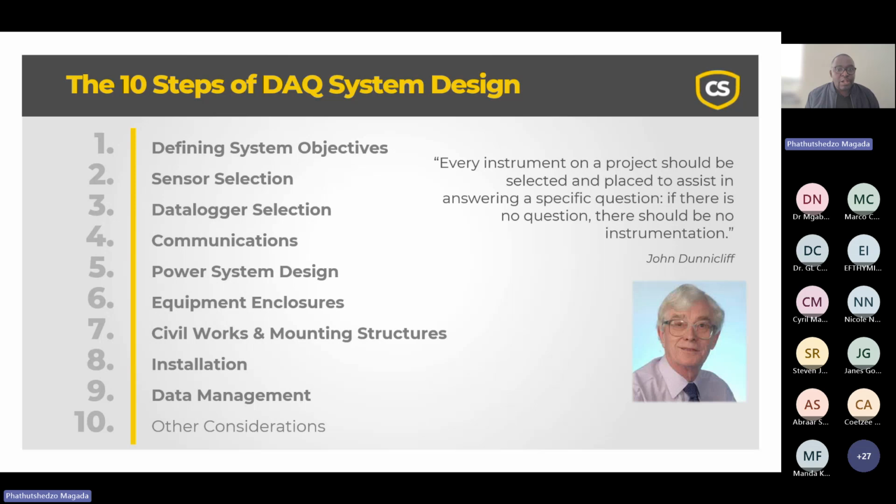Are we concerned with water level? Is there a concern about slope stability? And having done that, we will be able to choose the right sensors that, for example, talk to water level monitoring, slope stability, seepage. So we will then be in a good position to do that.